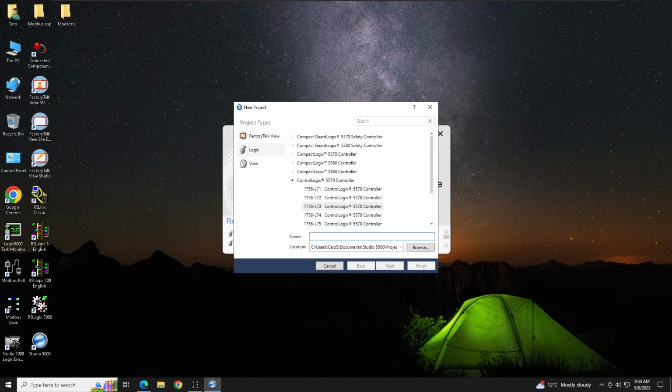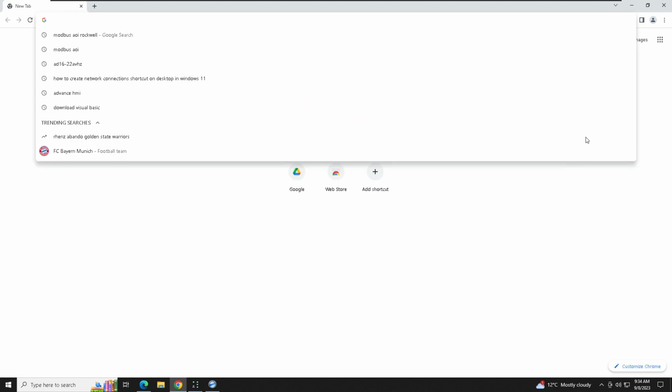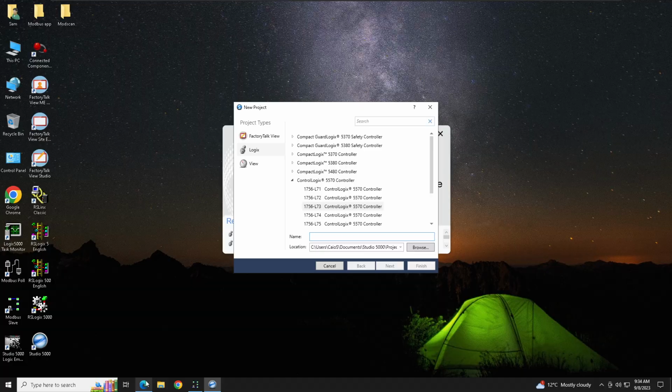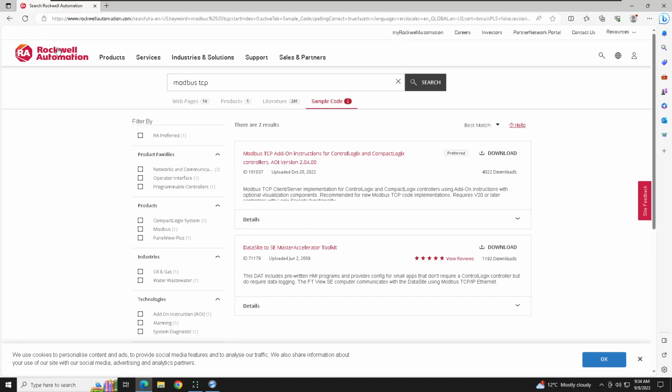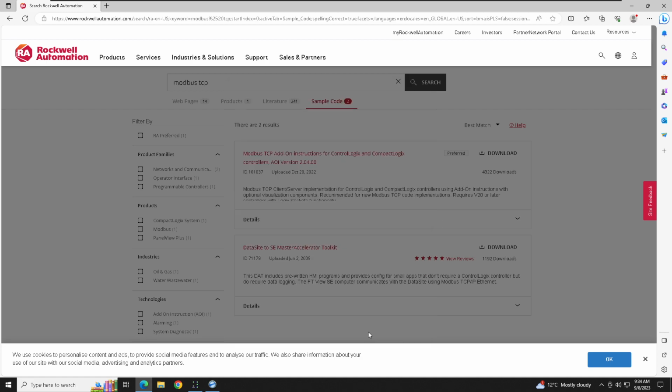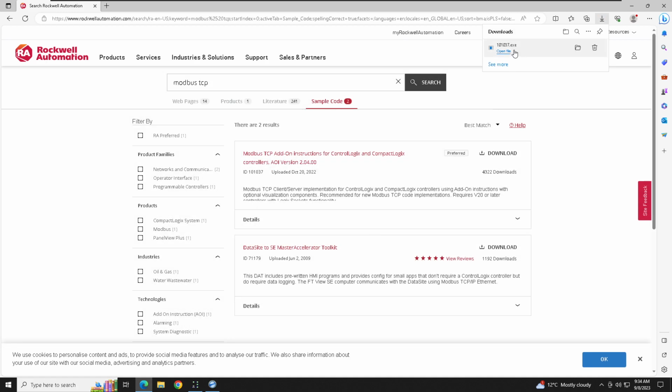Hello everybody. In this video we will discuss how you can use your ControlLogix as a Modbus client. For that, you can go to Google and search Modbus AOI, and once you search it, go to the Rockwell website and download this Modbus TCP add-on instruction. You hit download, agree, and it's downloaded right here.